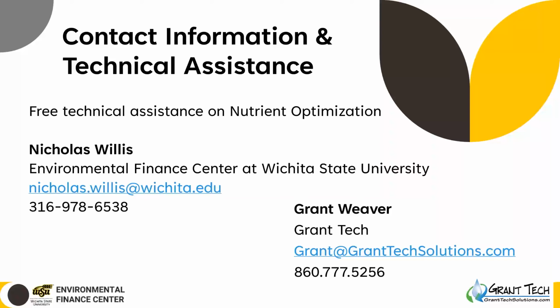I was talking about in the aeration tank for phosphorus removal, there can be an issue of not enough BOD. I just wanted to tell a short story in Iowa. Earlier this week, I had a follow-up call after visiting some Iowa plants. One of the fellows in Charles City had an anaerobic zone, anoxic zone, and then a huge oxidation ditch.